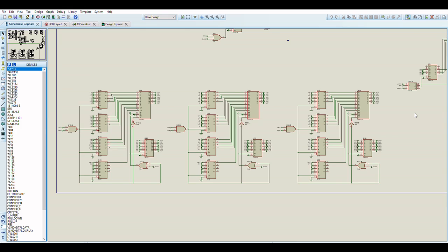That means you have up to 8 colors. Color 0 is always transparent, and colors 1 to 7 come from the palette data. So this is why we have 3 fast RAMs here, here, and here, with memory address line selection logic. Now, originally these were ROMs.